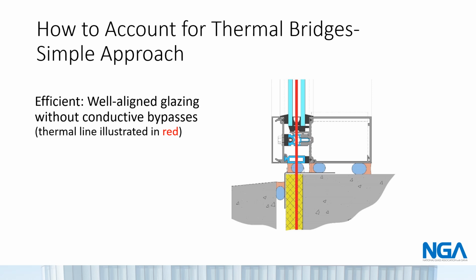This ideal is not always possible when considering the many functional design requirements regarding structural support, water management, etc. However, better alignment will generally result in less thermal heat loss and an improved or lowered psi factor. Note in the diagram, a flashing is shown which is exposed to the elements and passes beneath the curtain wall and into the warm side of the building. While this flashing isn't visible, surely condensation will occur and as such may cause issues.